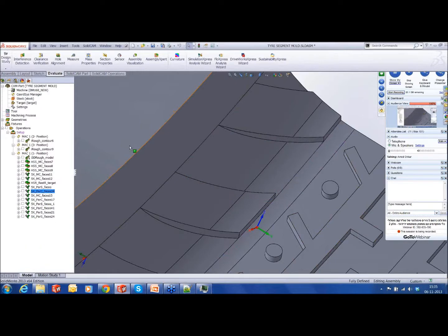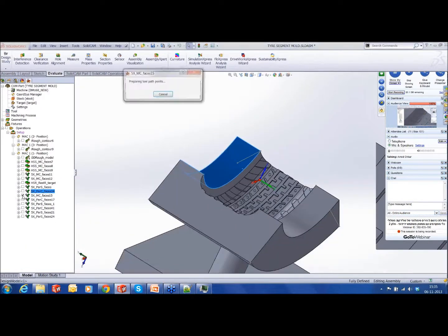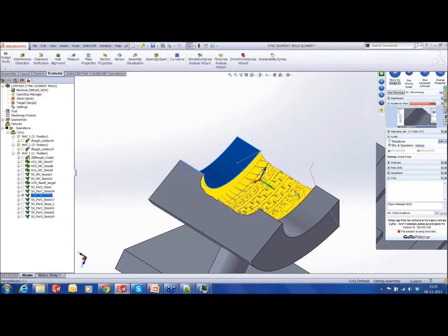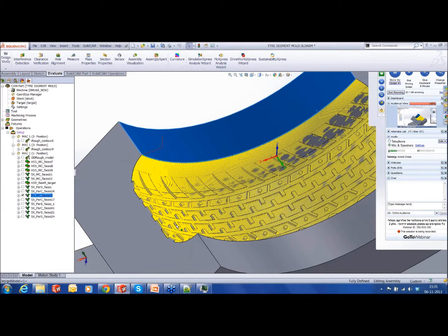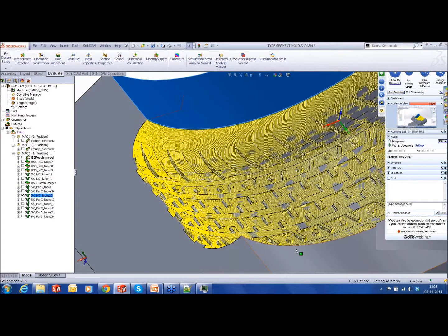Right. What next? Then we have used morph between two surfaces, or curves rather, to evacuate or to finish the entire thing. In fact, this is a pretty lengthy toolpath, and I've used the same principle that you saw in STL machining. I machined a dummy surface and then projected the entire toolpath on the entire projections. This is one way of finishing the mold. We have projected the entire toolpath from the bottommost surface up to the projections. So we create a simple clean toolpath, and like we did in STL, we project it back.